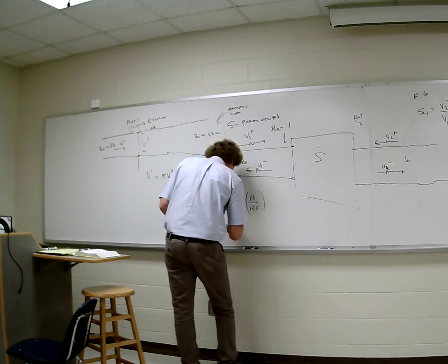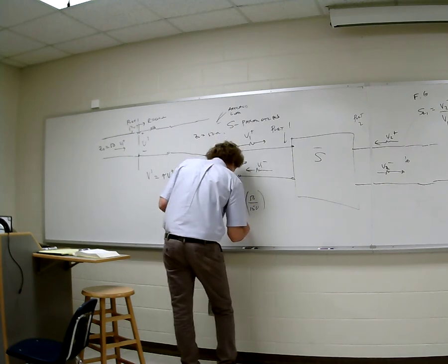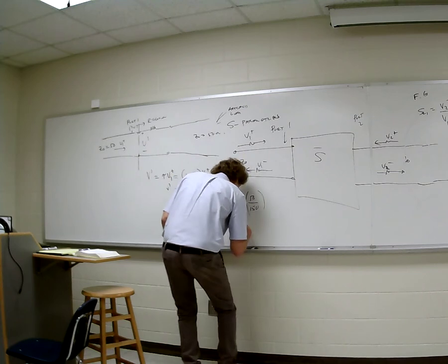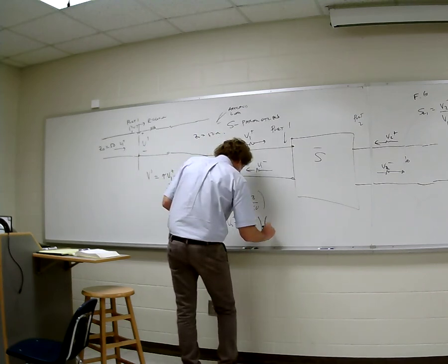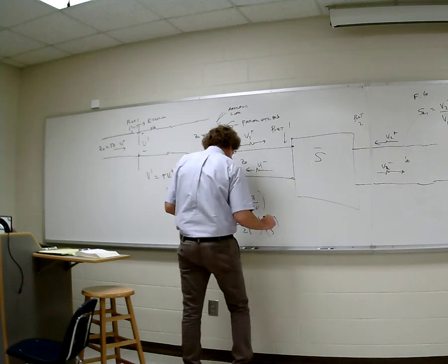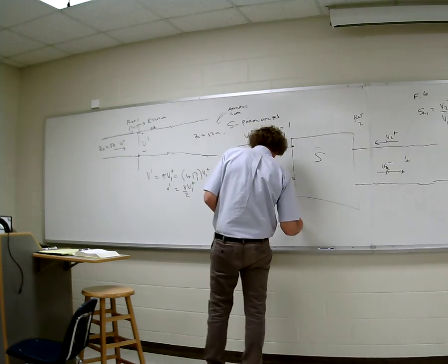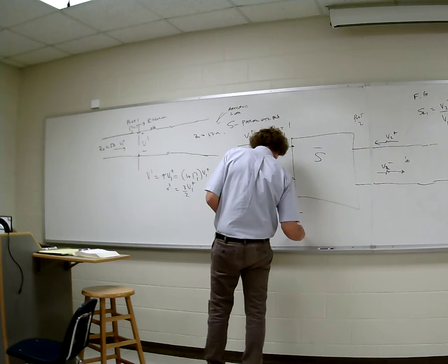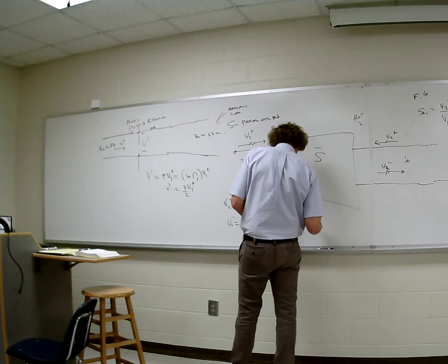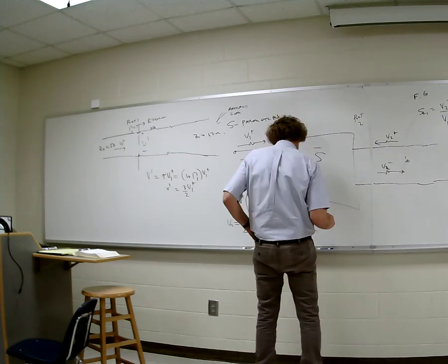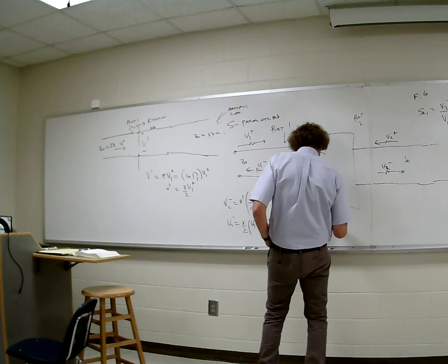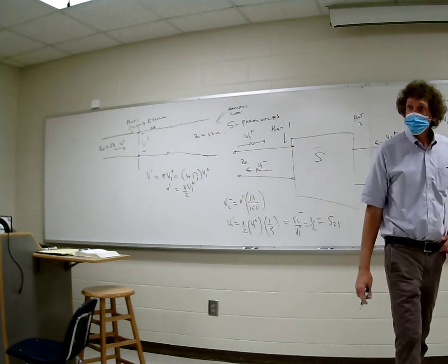So really I have V2 minus equal to 3/2 times V1 plus times 1/3, or V2 minus over V1 plus is equal to simply 1/2. Now you're going to take a look at that, and that would be S21. Do y'all see that?